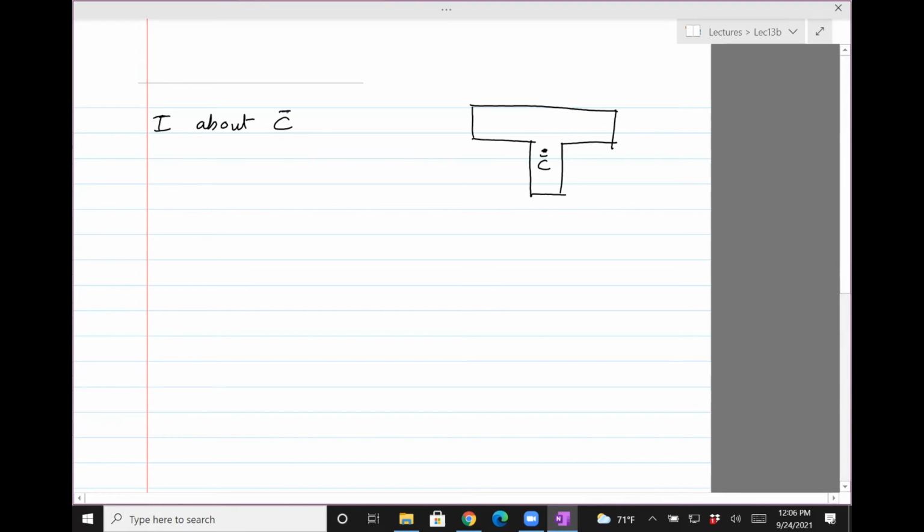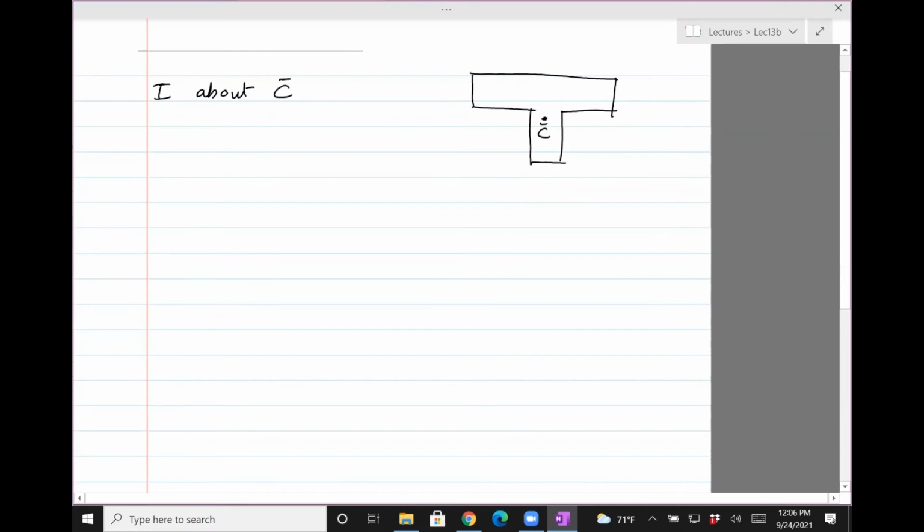Now, I don't know if you recollect this, but if you want to find the inertia about an axis which is not passing through the centroid, then there is a theorem called parallel axis theorem, which we need to invoke. This is a recap, something we might have learned in the previous class. So if you have a general planar body and there's a centroid, we need to find the inertia not about C, but a different point.